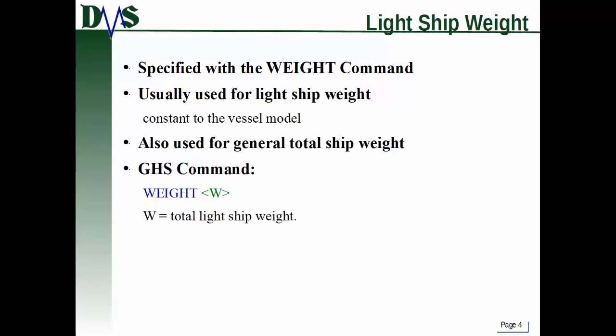And the command is weight, W-E-I-G-H-T, that keyword, space, and then the number for your total light ship weight. Make sure you check what your units of weight are. That's set with the units command, and that matters before you enter the weight command.